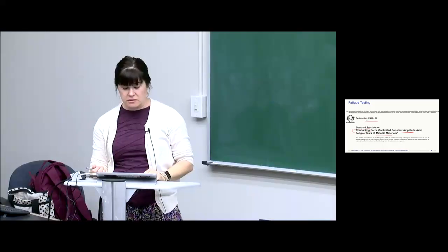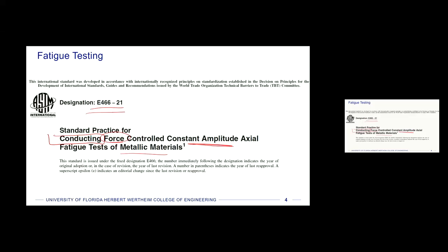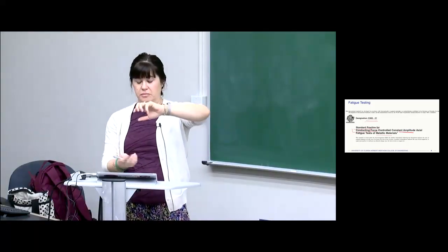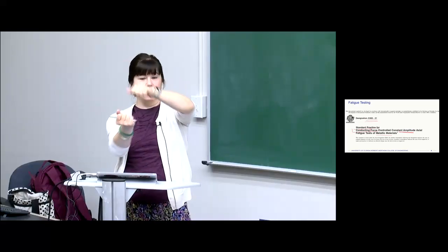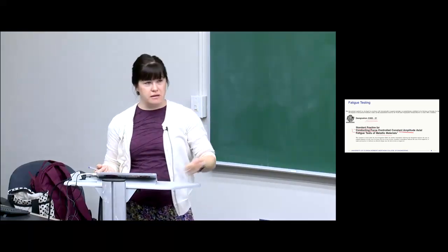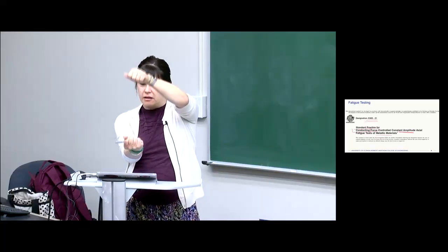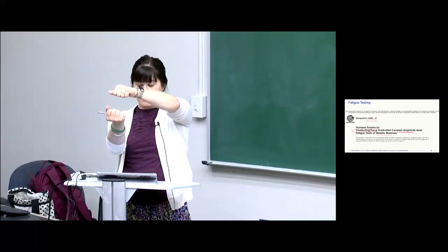And it's force-controlled. So we're going to be stressing a common specimen or a series of identical specimens to force-controlled levels, right? So we have to have force feedback on the load frame, right, in order to pull it up to some level of force and then release that force.